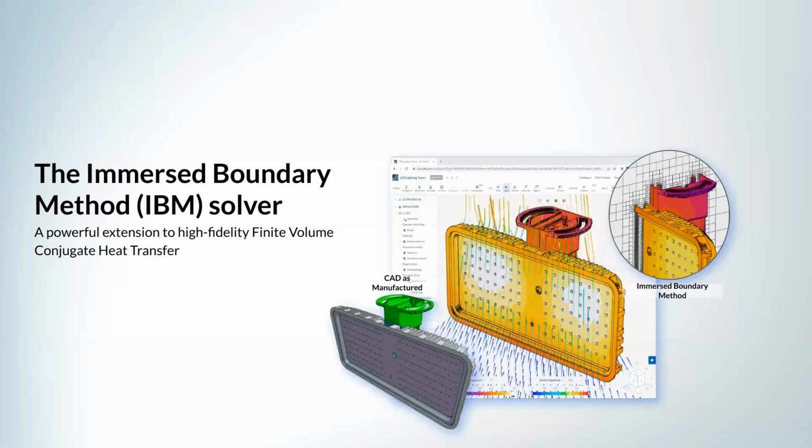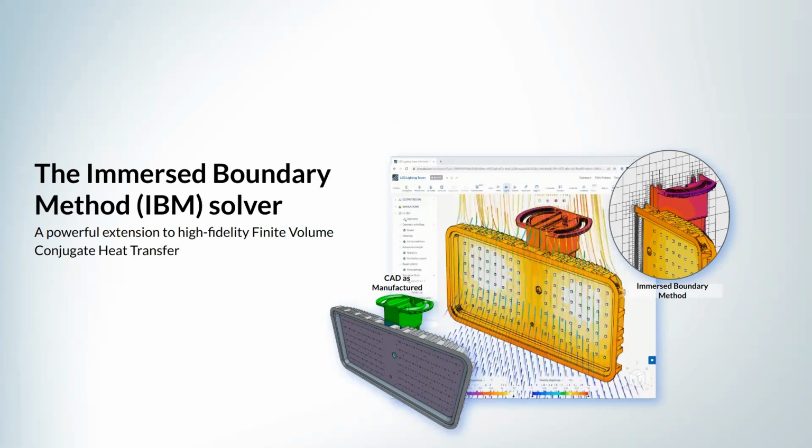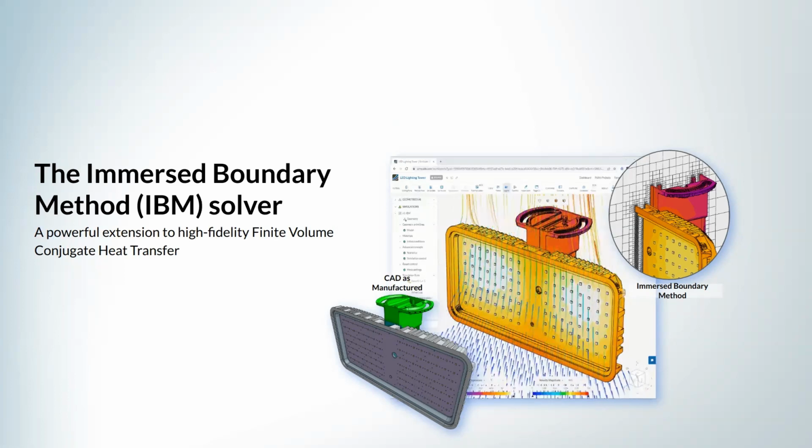Great. So with that introduction, I want to give you some insights into the Immersed Boundary Method and what it actually means. You can see here already some images. Also, you can see the meshing approach that is taken on the right-hand side. It's important to note in the beginning already that this is not a completely new solver. It's an addition on the conjugate heat transfer offering that targets thermal simulations in general. So it's really an extension to this solver that just changes the way how the meshing is done and how we can treat original models.